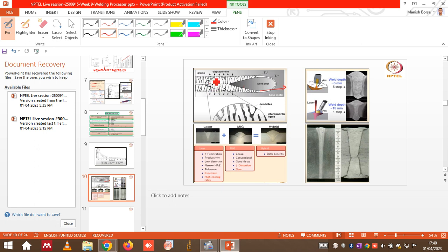Okay, so that kind of hot cracking can be a problem in certain alloys when a higher cooling rate is provided. But we have also seen that laser welding can be used in different ways. Let's say if you want to weld a very thick plate, then we can use the proper laser source and welding parameters and ensure through thickness, or the keyhole mode of welding.